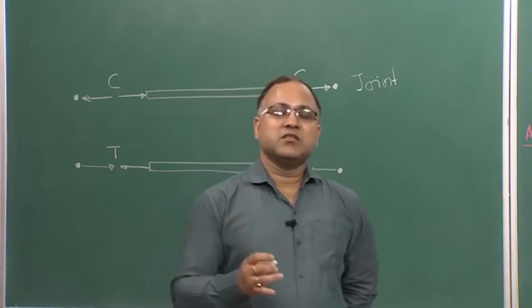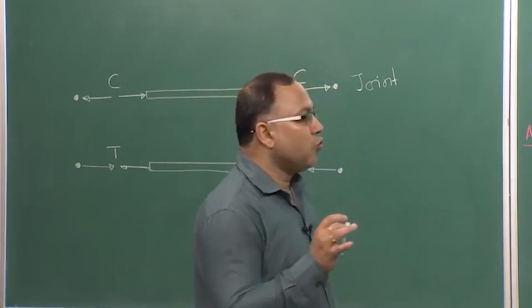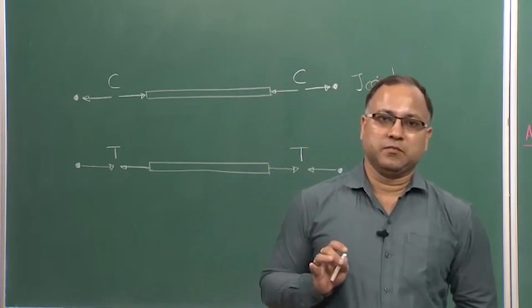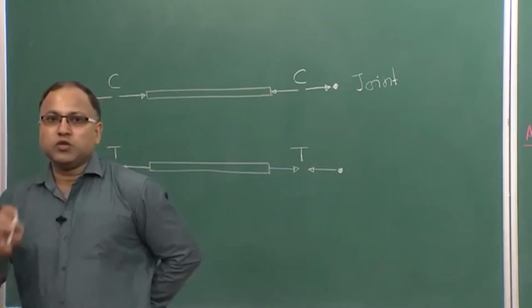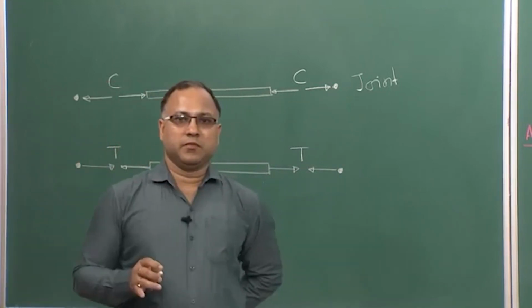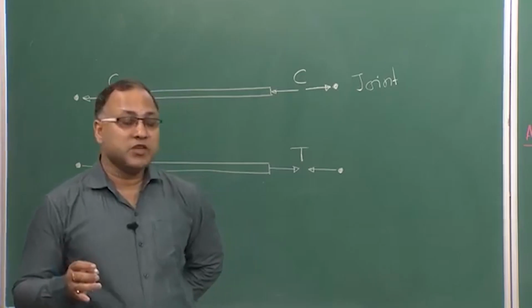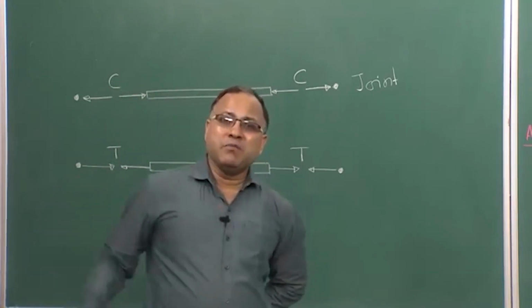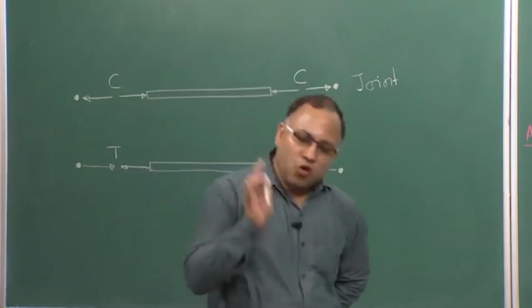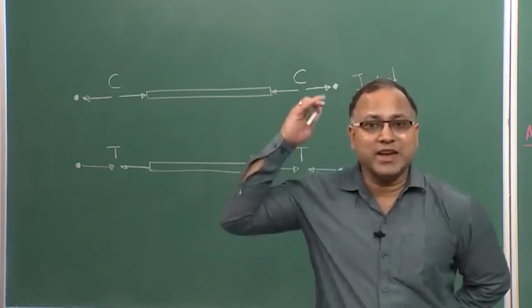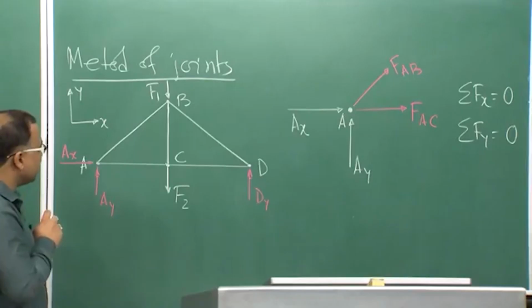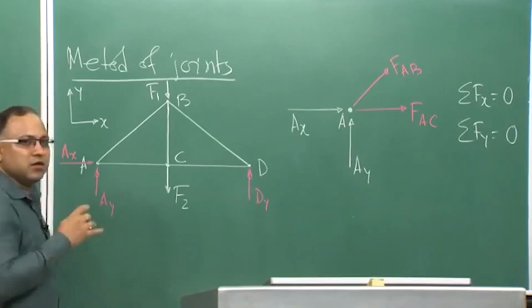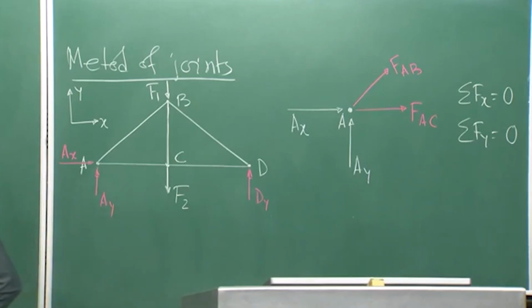Okay? I just considered that these forces are tensile in nature, and it is always advisable to stick to a particular assumption. What is that particular assumption? That you consider that all the member forces are tension or all the member forces are compression. Do not scratch your head, oh, this force will be compressive or this force will be tensile or what will be like that. Do not get confused there. It will be coming automatically.